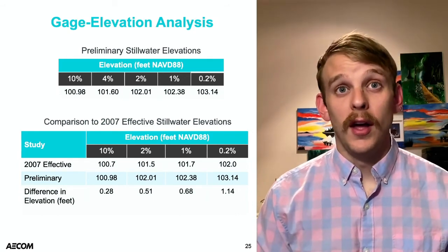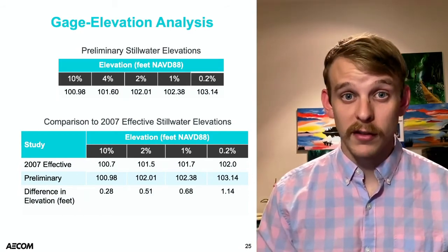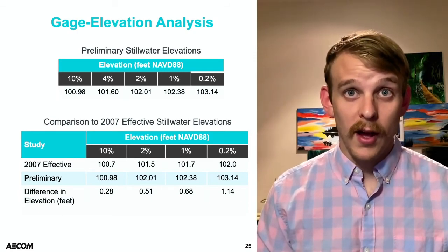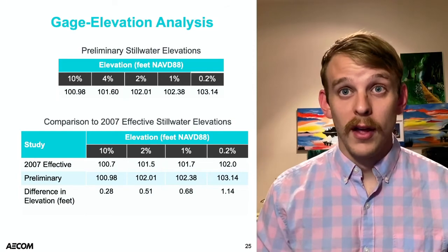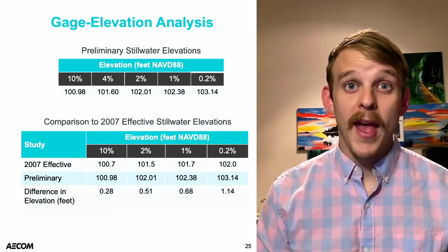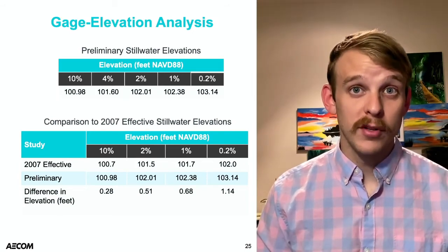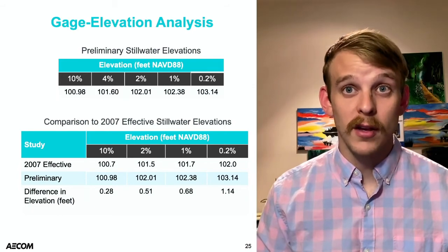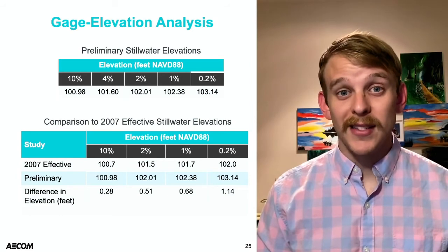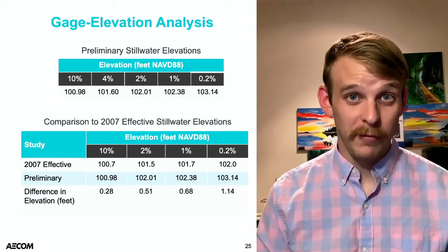And now I should reiterate that the effective study for Lake Champlain used a graphical frequency analysis with one gauge station versus our use of four. And the age of records was a lot older. And for mapping purposes, for the effective study, the 1% and 0.2% floodplains, also known as the 100-year and 500-year, were mapped based on 1966 topographic data of contours of 10 and 20 feet.